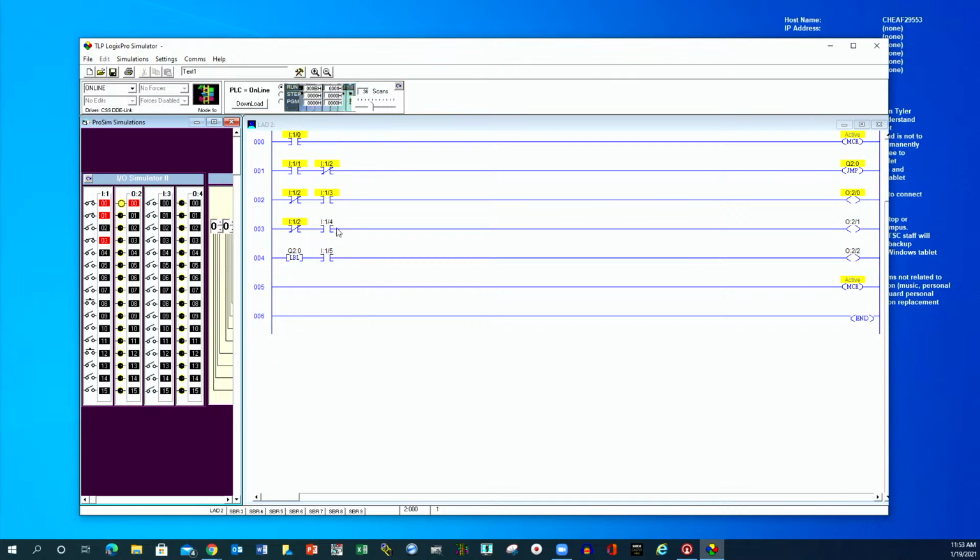But I could make a conditional return somewhere and say, okay, I want you to return on rung 3 because I don't want to read rung 4, 5, and 6. I want to leave early. And this doesn't make much sense with a short one, but if you had a super long one, maybe whatever that subroutine was meant to do was already accomplished. So you don't need to keep on doing whatever is down the rung. So you can say return, and it will return back to the main.